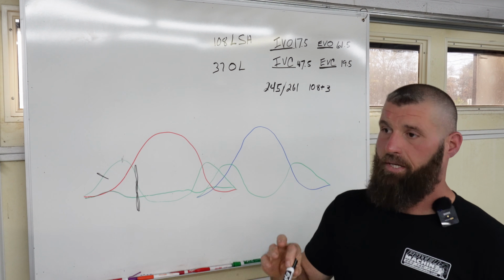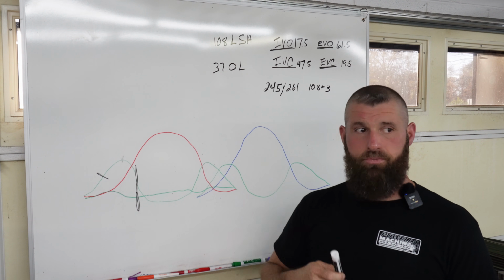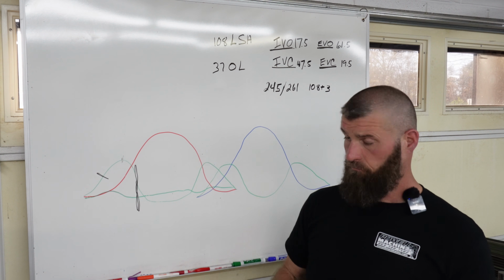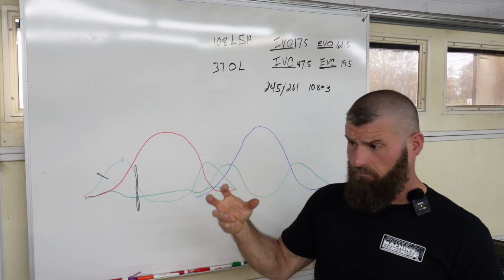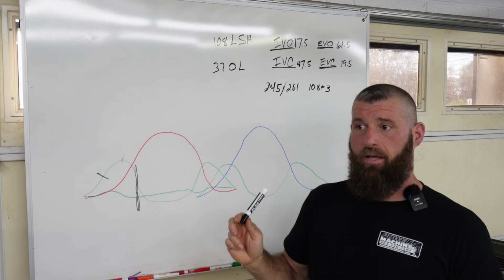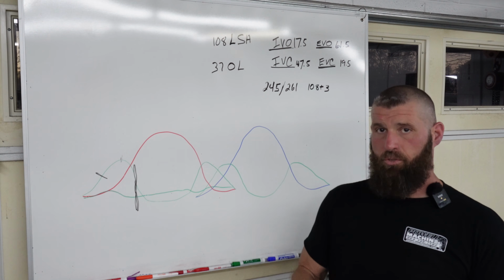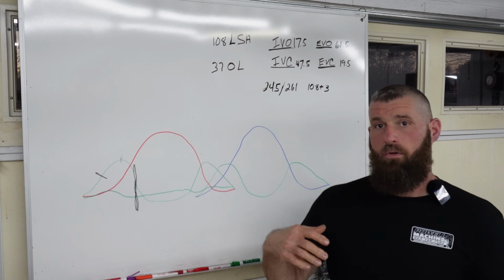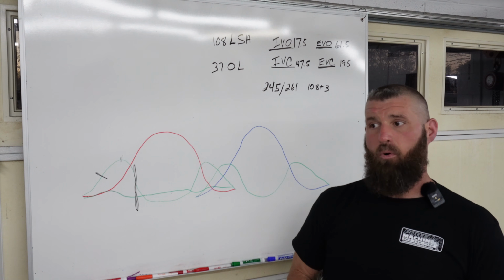So that's why it's so important. Jim Bob calls XYZ company or gets some guru on the internet to spec him a cam, and all of the right questions weren't asked, and they weren't applied to the system. So we end up with lobes that are incorrect for the application. You're just beating up the valve train, with a super noisy valve train, or you're potentially leaving horsepower on the table. All of those things are why getting this stuff right is really important to me anyway.